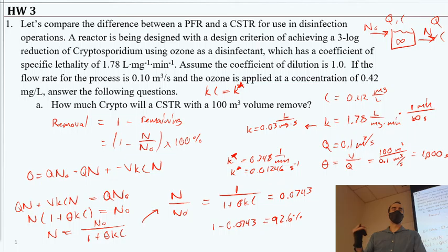There are plenty of problems that say something like this: this chemical is injected into the system at a rate of, and then it gives you mass per time. And if you're stuck in the bubble of thinking about it each Q, like a mass per time, for example, Q times C gives us mass per time, right? If you take a look at the units, that ends up as mass per time.